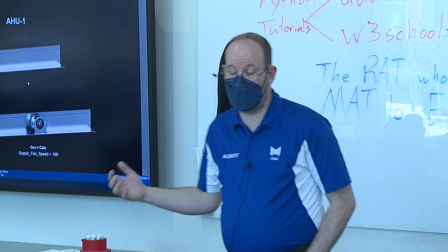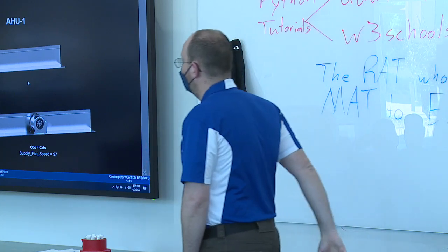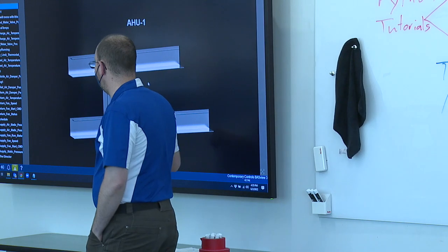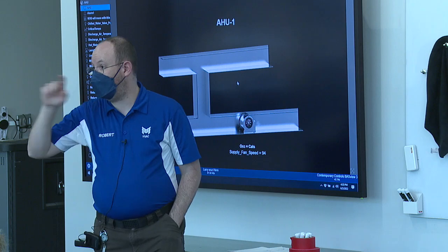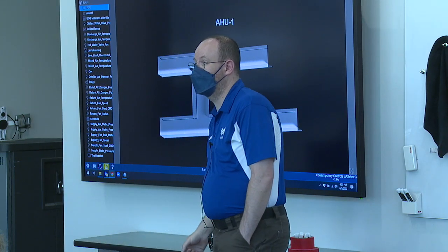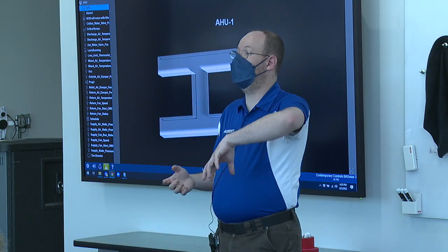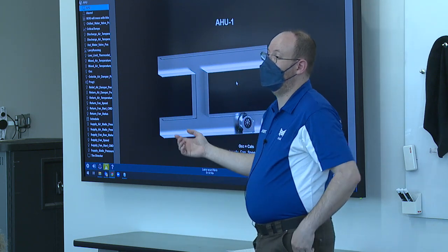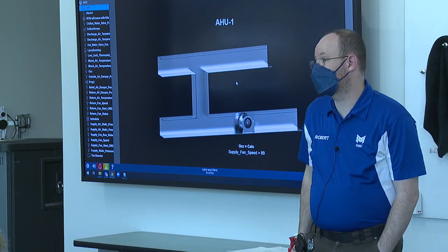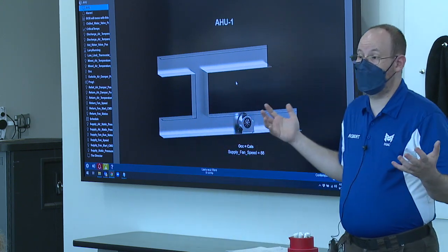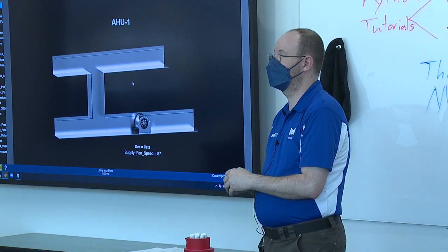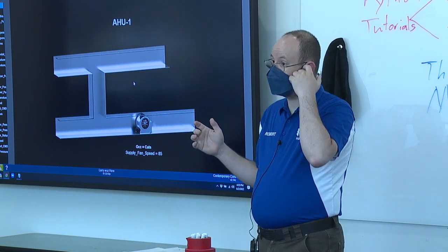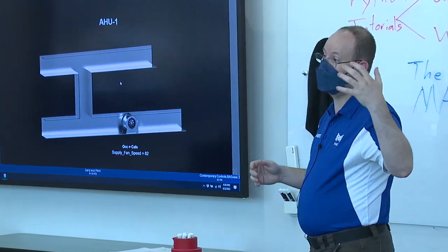Or if it's one specific thing in the VAV boxes, like just program 1, you save that individually as a template, go in, blow out program 1 in each of your 50, and copy it in as a new template. Is it ideal? No, you should have done it right the first time. But you're right, it definitely does happen. Some systems, again, make it easier, some systems less so.